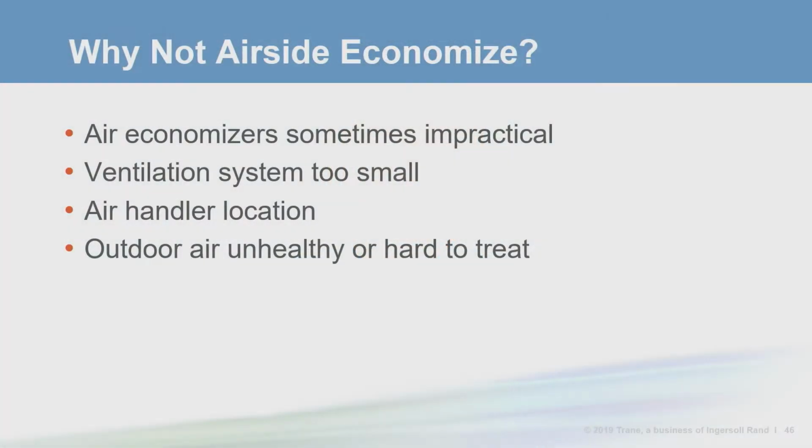Now, it's generally agreed that airside economizers save more energy than water economizers. Dustin, could you help us understand some of the reasons why an airside economizer isn't an option? Well, Susanna, the reasons could be the type of system, duct size or building limitations, proximity of the main air handler to a suitable location for outdoor air, or the quality of the outdoor air and our ability to clean it adequately. But in the case of hospitals, museums, or other special purpose buildings, we are often looking at humidity requirements. That is, the impact that bringing in too much outdoor air has on our humidification loads when the air outside is cooler and drier.